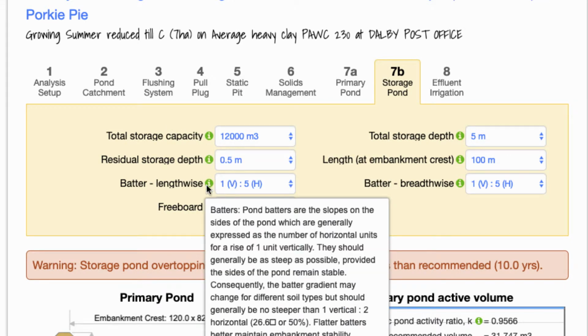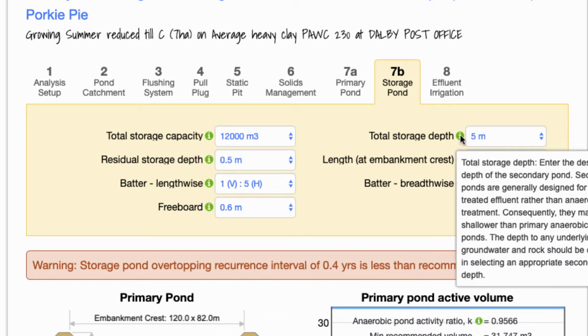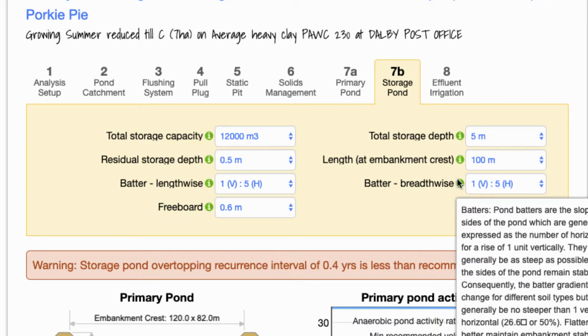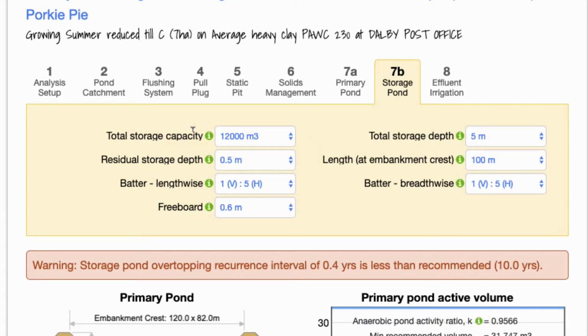The size of the storage pond should be sufficient to store excess effluent, not required for shed cleaning during periods of extreme or extended wet weather, when the soil in the effluent irrigation area is too wet for effective effluent application. If the soil water storage profile in the effluent application area is relatively full, further application of effluent onto this area may result in runoff and or leaching and possible export of nutrients and pathogens which may contaminate surface water and or groundwater resources. Regulatory agencies generally specify a minimum spill reoccurrence interval, typically 10 years, to minimise the risk of spilled effluent contaminating the surrounding environment. This design standard may be varied depending on the sensitivity of the receiving environment.